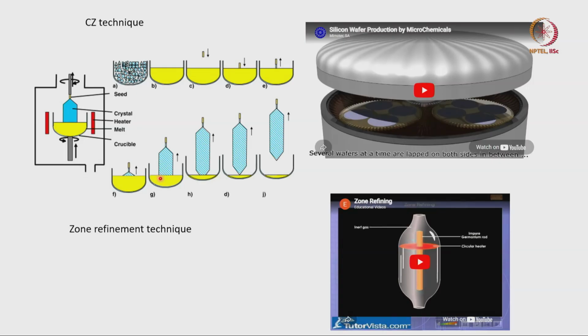Once the silicon nucleates, you start spinning it and taking it out. Once you are taking it out, this silicon is colder, so this region progressively gets colder and colder, and my nucleus starts to grow in this direction. So I am making it grow in a very slow fashion.